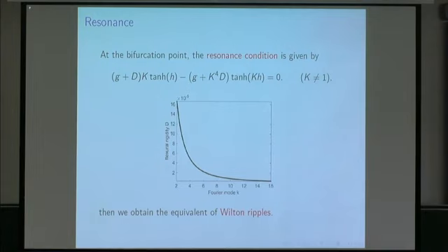So what happens is, at linear order, you obtain this relation. So you can do a plot. Depending on what your value of flexural rigidity d is, if you say that your linear solution looks like a cosine, you'll also have another higher frequency cosine showing up at linear order as well. You can relate it by just doing a plot of this in terms of d versus k. What I'll often do is vary d in order to get a particular Fourier mode to resonate with my first mode, my plane solution of a cosine.